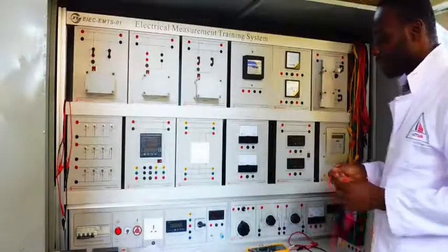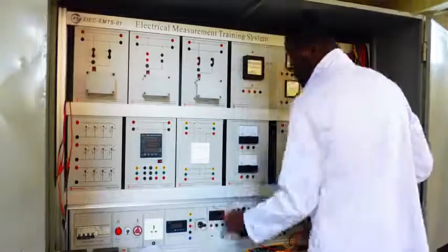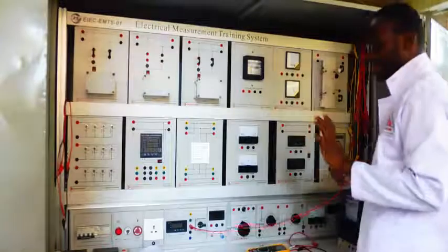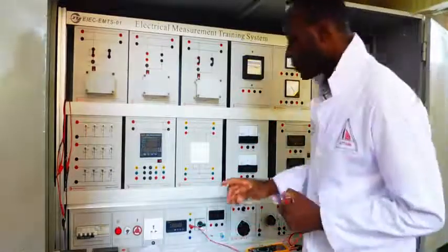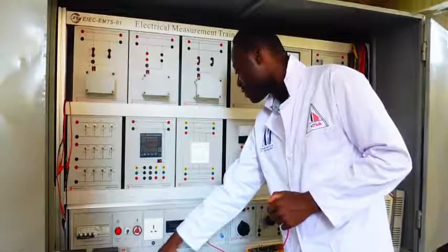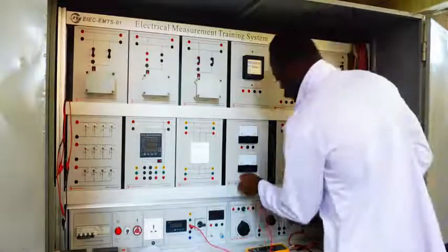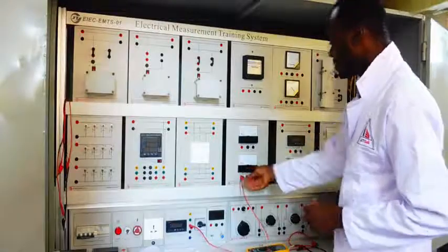Let's start from the live wiring. So this is our voltage source. We'll pick one phase because it's a single phase, so we are picking the red phase. Now, from the red phase, according to the wiring diagram, from the voltage source, we go to the ammeter. So this is my ammeter. Now the ammeter is in series, so live input and live output.